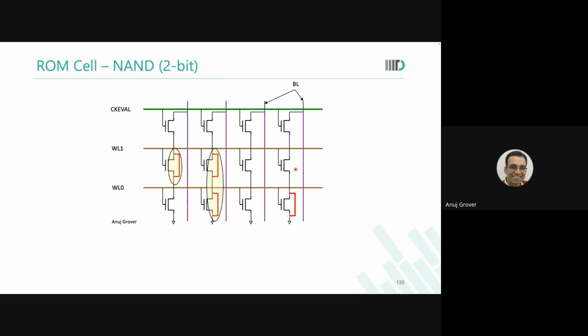We have flipped. Flipped means not data flip. We have changed the way word line is to be handled. The state machine will change. Your control block will change. Are you able to see this? As you transition from NAND to NOR gate or vice versa, your control logic changes completely.